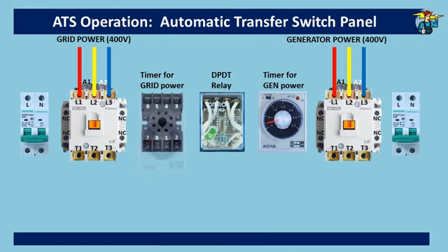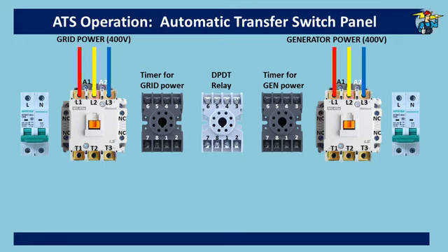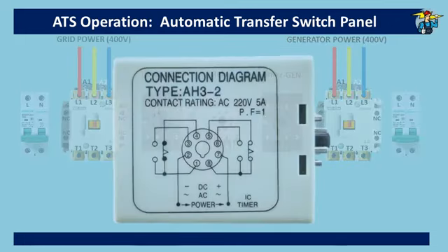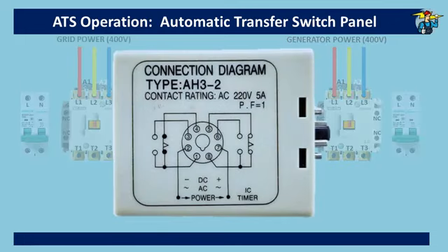When you take timers and relay out of their bases, you will see the numbered ports like this. On this picture you will see how the positions are numbered for the normally open and normally closed positions, and also the common points and the power supply points. Power connection for the relay or timer is to be given through the points 2 and 7 according to the details given on it.